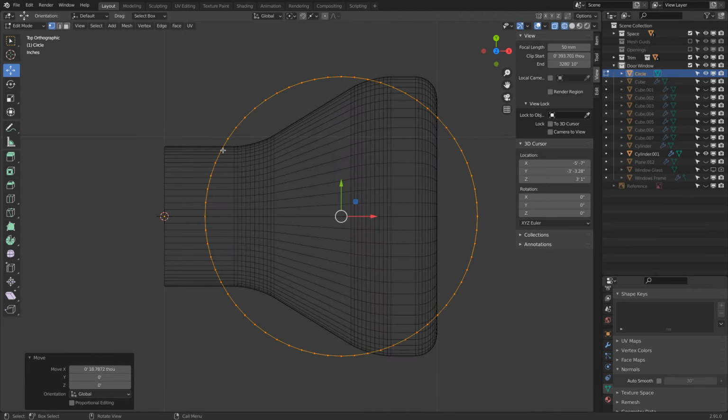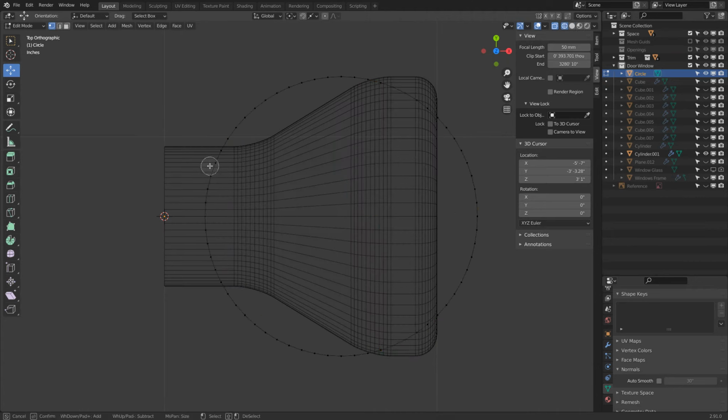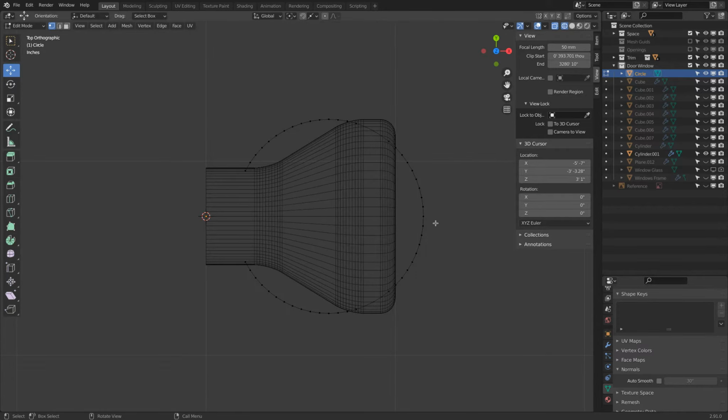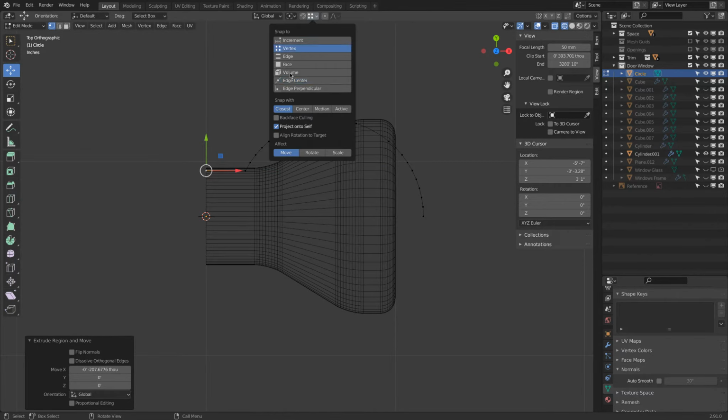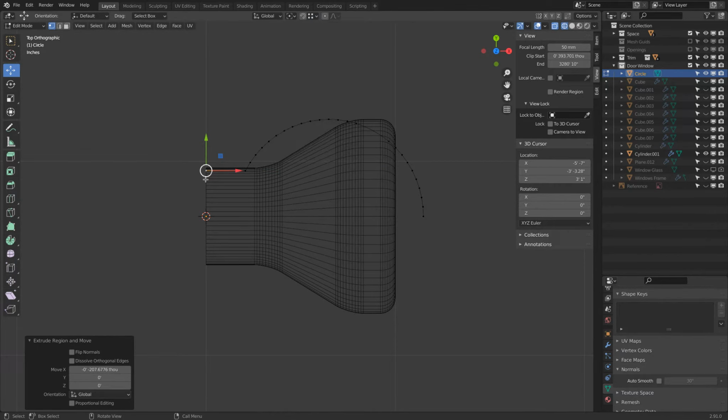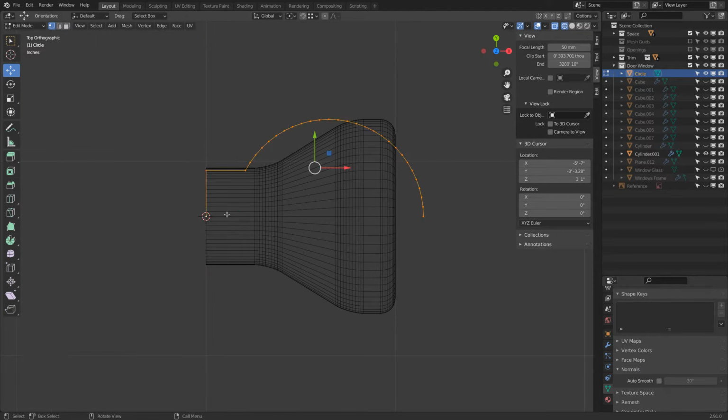And A, we deselect all this, and then here's the center, I will select and delete. Select this one, E and X, snap actually here to the geometry, vertex, and then E and Y, I snap to there. This is important, because this is the midpoint, no?